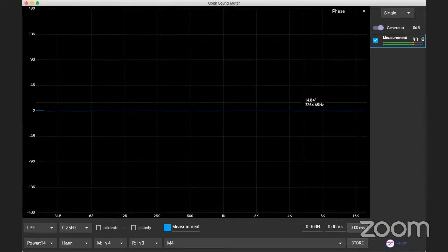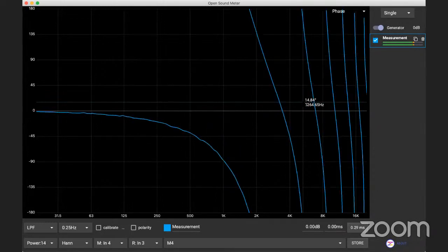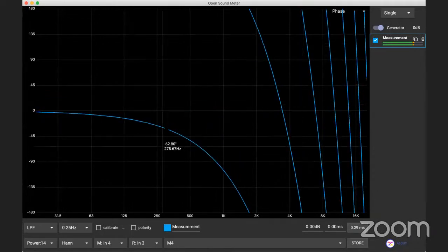So you're measuring this value in reference to the reference channel, right? Yeah. In this case, whatever is coming out of aux number 3 is my reference. So right now, what's coming out of aux number 4 is in phase with aux number 3. The moment I put this delay on the console, I have a feature of delaying any output. So I'm going to deliberately delay aux number 4. The moment I delay it, I can actually see the delay on screen, and now I know aux number 4 is getting delayed compared to aux number 3, which is at 0.